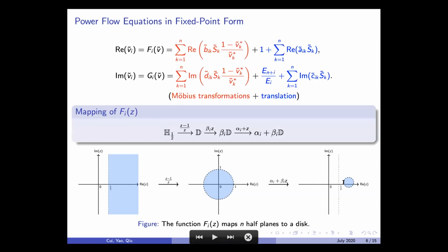So an easy corollary of this is that if we can certify solution existence, we can also certify there is a unique solution with voltage real part greater than 1/2. So if this is where the high voltage solution lies, then yes, with the uniqueness condition, we can certify that this is also a unique solution in this half plane. But without the uniqueness condition, of course, we cannot know whether there are other high voltage solutions.